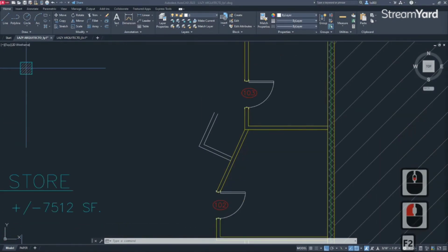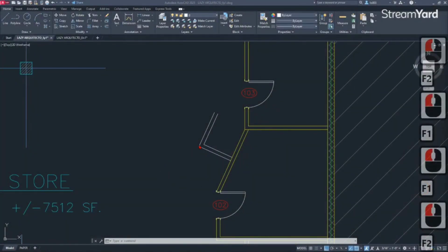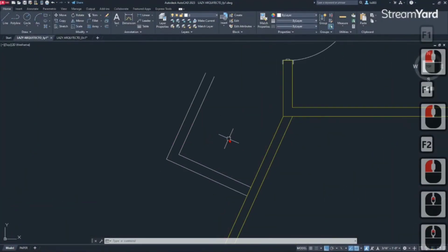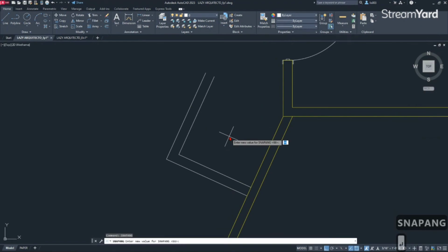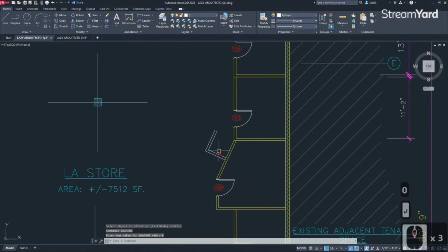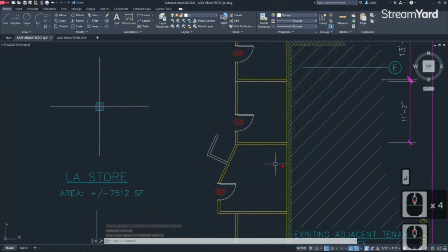Great, right? So that's again, before we proceed, I wanted to show you how we can set the angle back. We can use the snap and set the angle in this case to 0. And once we do that, again, our cursor is straight. So that's a productive way to draw in certain angles in AutoCAD.